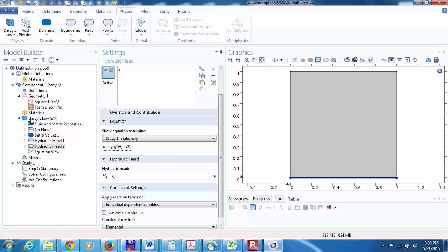Instead, we're going to calculate boundary fluxes by an alternative method, which the user's documentation for COMSOL describes as just another approach, an alternative approach. It's not clear to me exactly how it does that calculation, but it does yield the same results that the Lagrange multiplier approach yields. So that gives me some confidence that it is working properly.